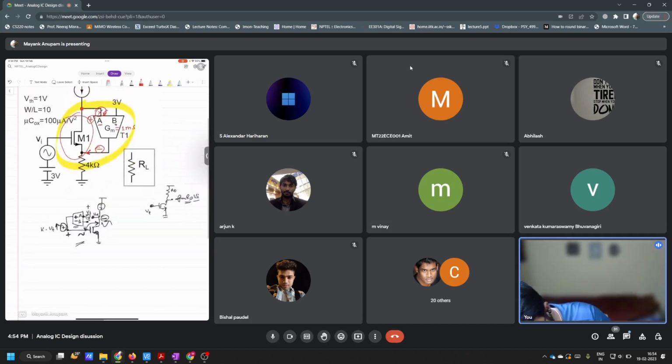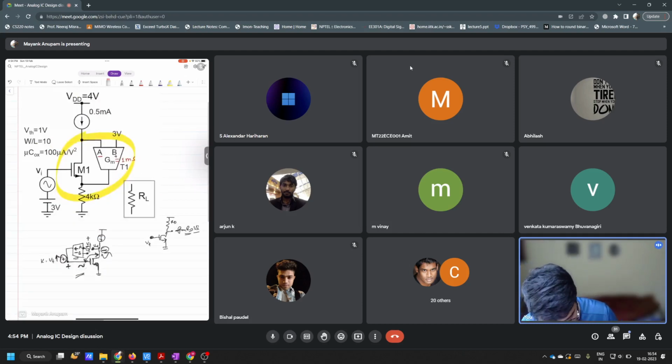So yeah, this is a common gate structure. If this is negative here, this will also be negative here, right? So you see the input was plus applied at this node, at the A node, and the return voltage is negative. So the return is an inverted version of what was applied at the input. That is why, for correct negative feedback, A is negative and B is positive. Cool.